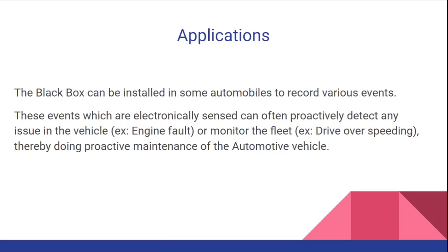It is 8-bit. It contains 5 ports, namely Port A, 6-bit, which is analog. Port B, 8-bit, is a bidirectional port. Port C is also 8-bit, digital pins used for serial communication. Port D, 8-bit, all are digital pins.